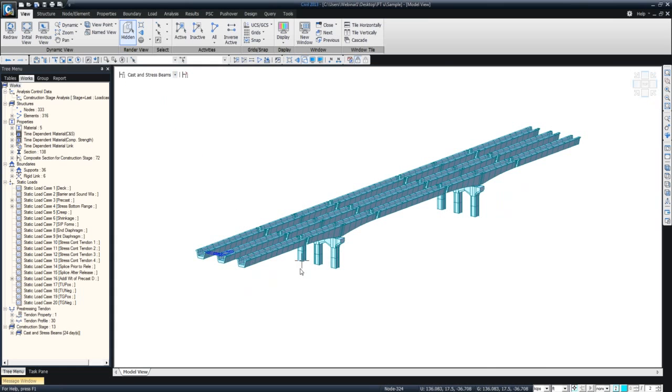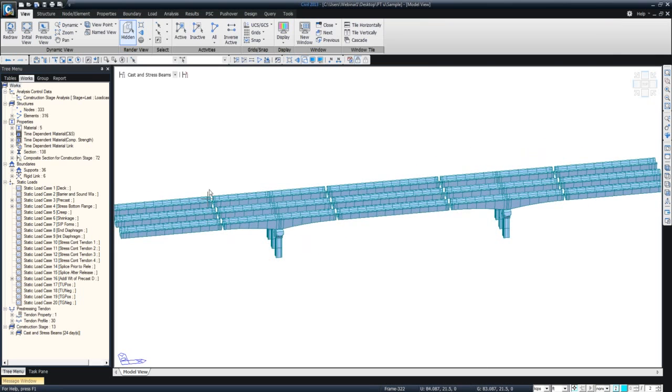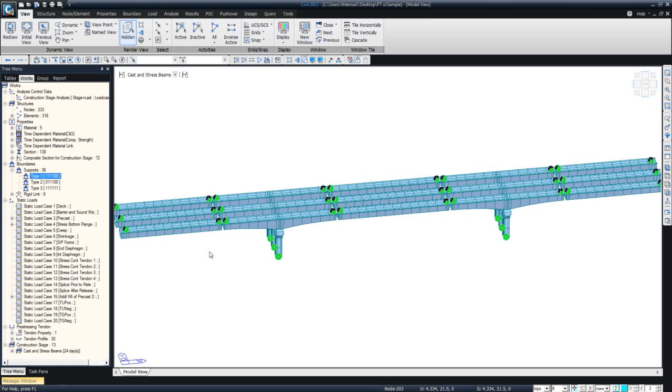Then we'll have the U-tub sections there without any cover, just the bare girders. And if you see right here, you can see the splice gap there, so the members are yet to be applied. So even though you cannot see the shoring here, it's a very popular method of using point supports at these locations. So if I turn on the supports, you can see there are some supports applied at the splice location. So these point supports represent the shoring for you.